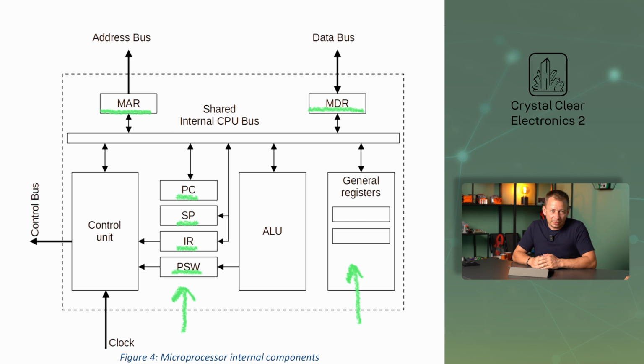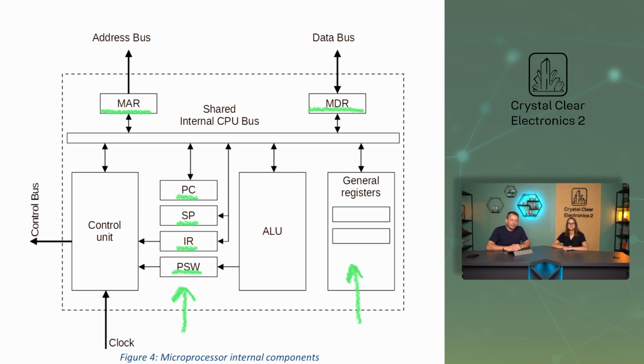Next, it performs the addition, and the result is written to the general register R1. Finally, it writes the value of the general-purpose register R1 to the location of the variable c in memory. It's clear that general-purpose registers are essential components of the microprocessors used to execute instructions. It is important to point out that all instructions that use general-purpose registers work in a similar way to this.